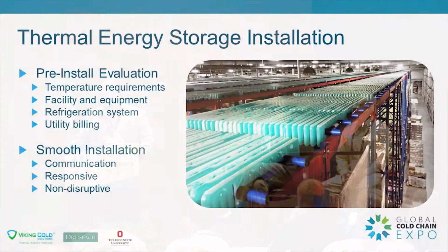So for us in Northern California, a lot of our costs of refrigeration are based upon time of day usage, demand charges, and other economic factors that are put upon us by the utilities. What do we do to try and manage those costs? We pre-cool down below 0 degrees, trying to get to -7, -8, so that we can achieve some period of cutoff to try and defray costs during that period without jeopardizing customers' products. Or should we shorten the floating periods that we allow the product, the warehouse to be on, so that we stay within our customers' parameters.